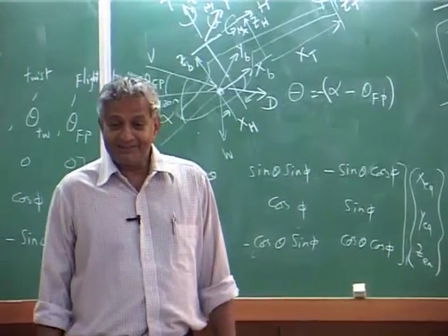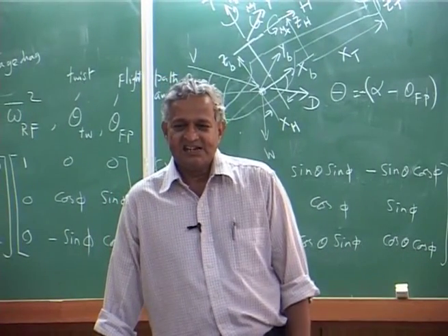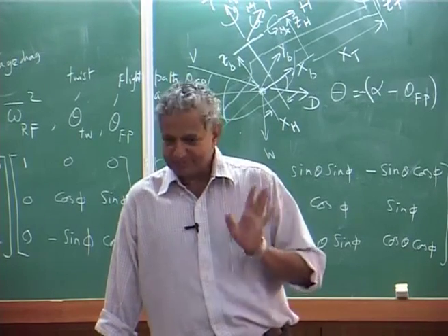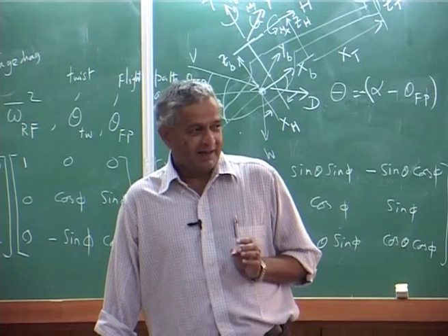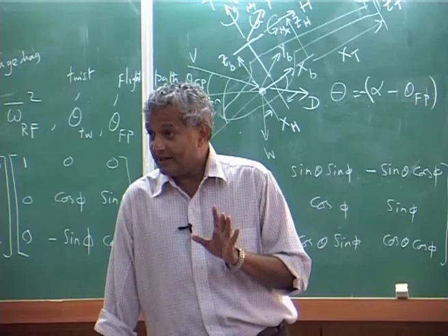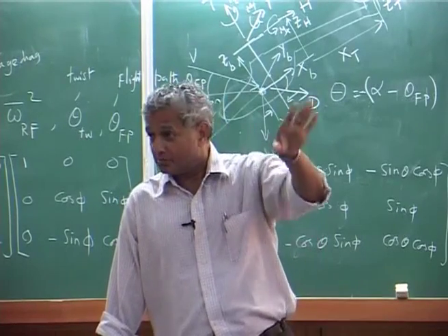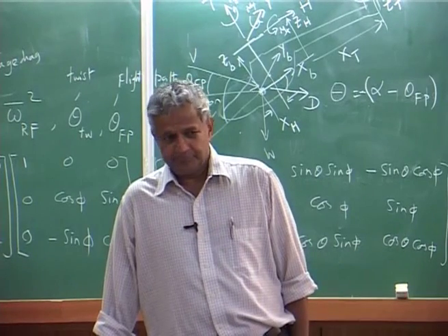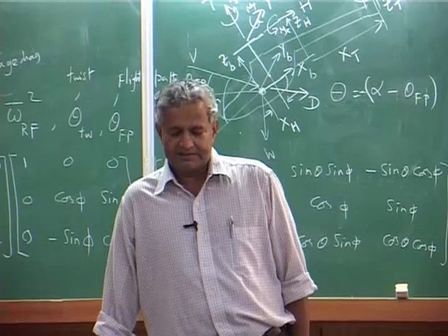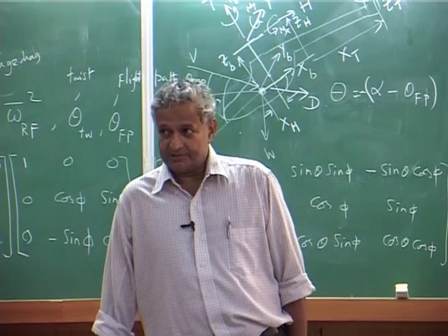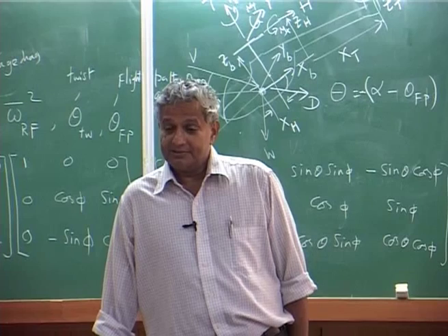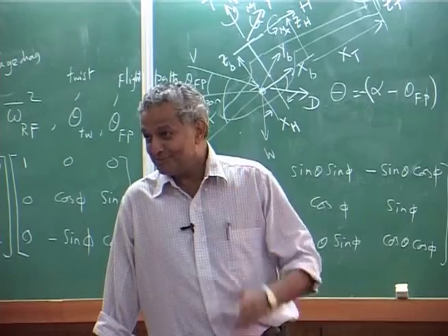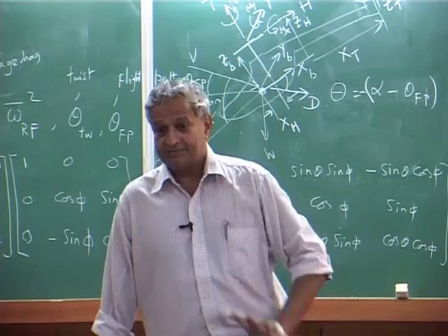Is there any logic to decide what angle they should give? Most designs will have 0. Some helicopters have some angle. And I have to be very honest, I only know the effect of this is it will give some component. You need to have a tail surface always. If the helicopter has to fly at a slightly higher speed, you need a tail surface. Why? If you do not have one, you will not get moment equilibrium, which means you cannot fly the helicopter at that speed.